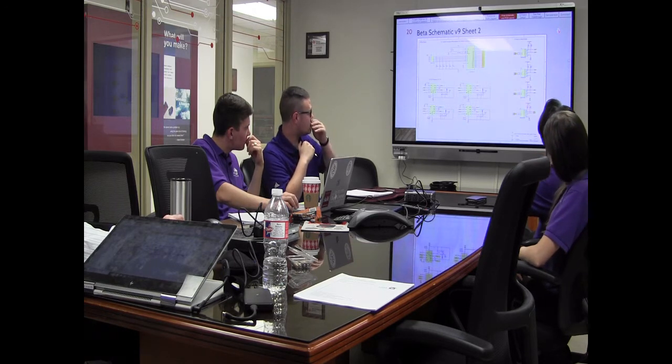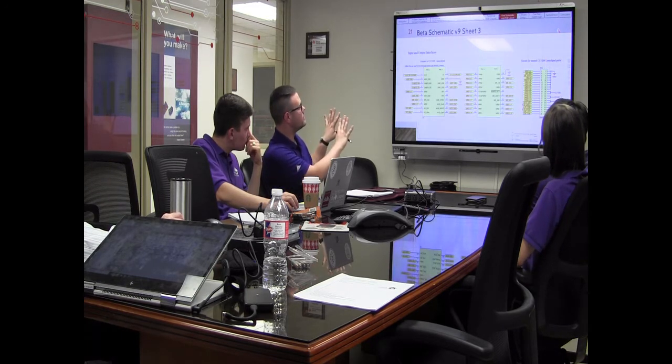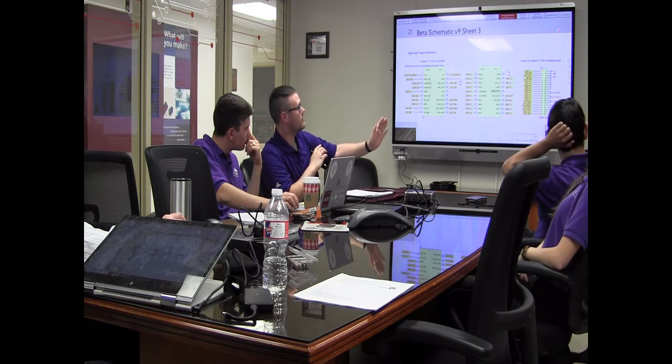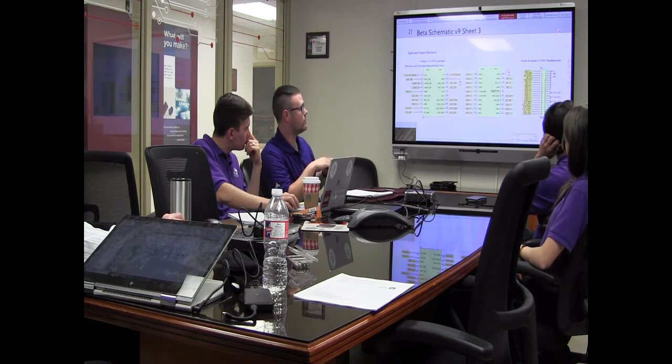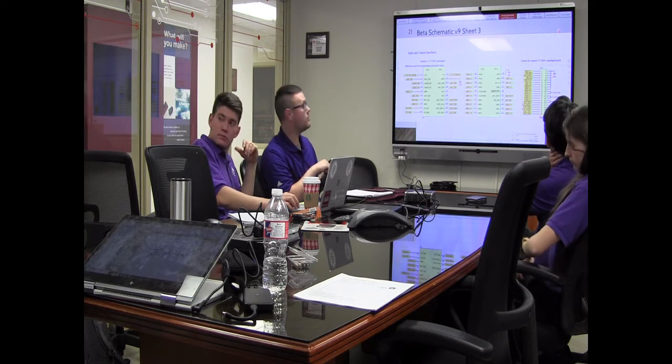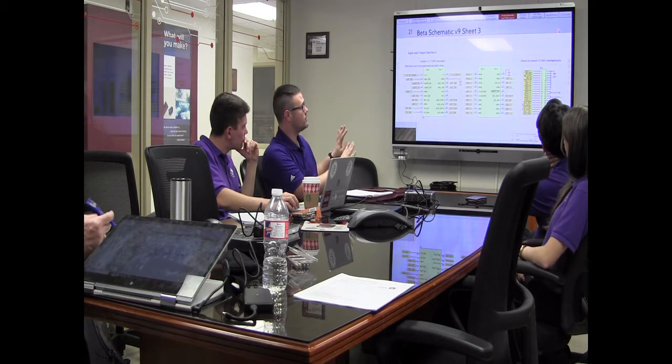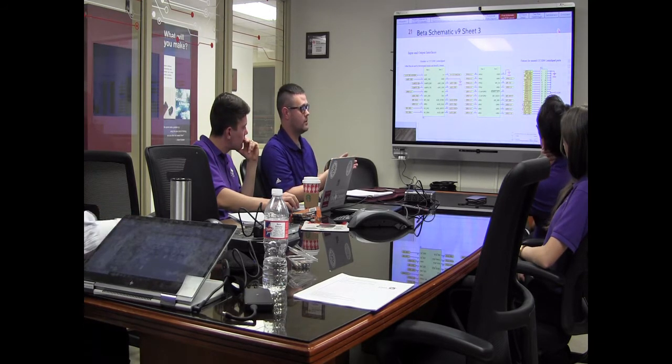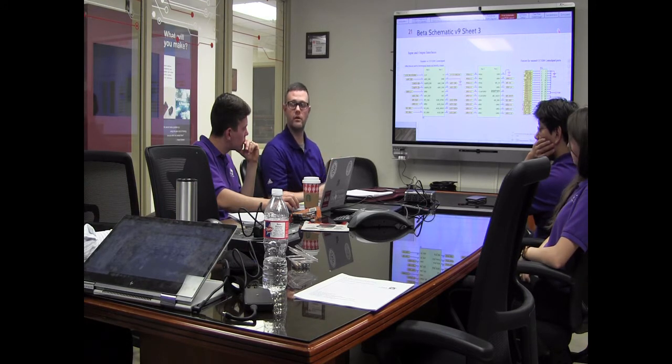So there's all 4 of those on the right-hand side. Go to the next sheet. Here's the launch pad headers, and then on the right-hand side is the fan out for all the unused CC3200 launch pad ports that we aren't using, as well as a couple 12 volts, 5 volts, 3.3 volts, and tons of grounds. So we have lots of options, as well as these CC3200 pin headers are male and female, so you can just stack a board on top of or below. Our board doesn't really care, just as long as it's pointed in the correct direction.